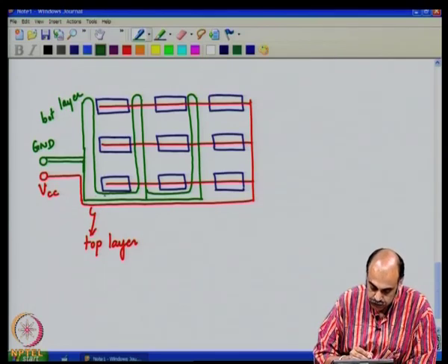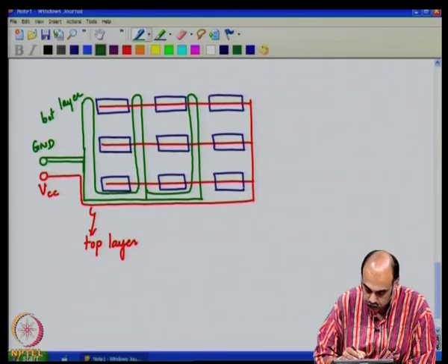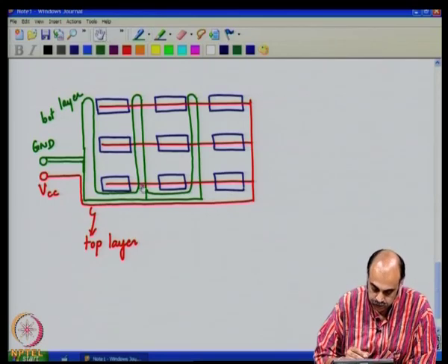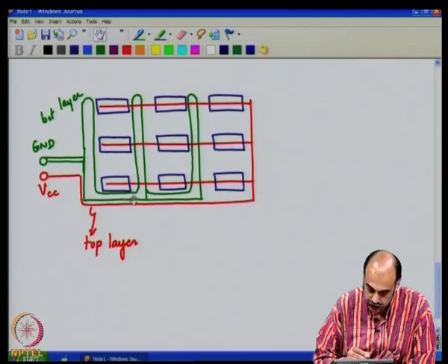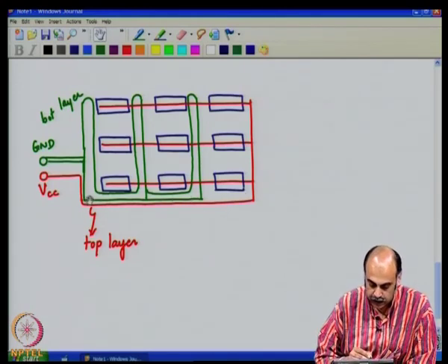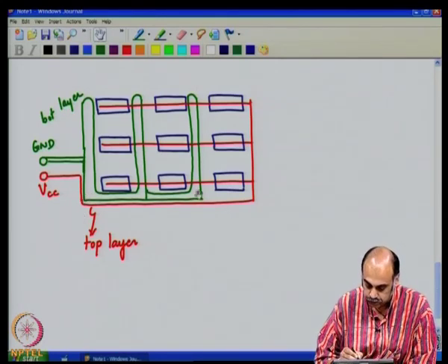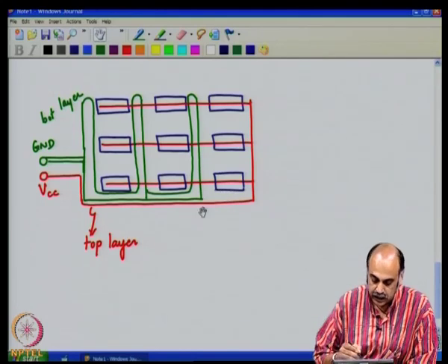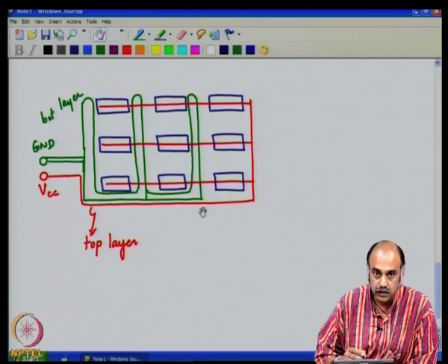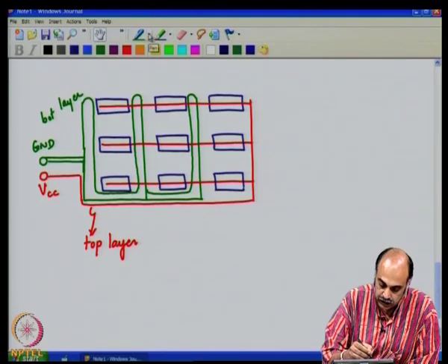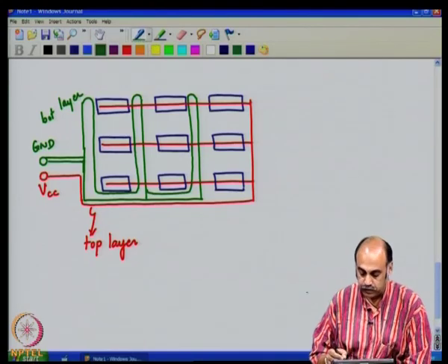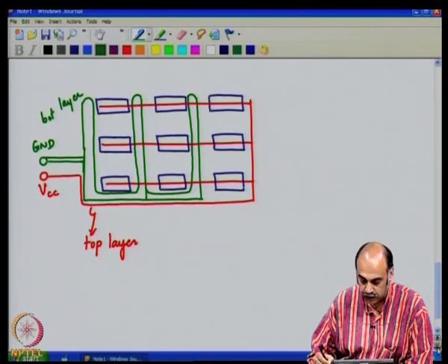Now, by trying to keep majority of the ground and the supply here in this zone, you can make the ground very thick, ground tracks thick here, and then the supply on the top layer to overlap on the thick ground layer, so that you can try to have a good level of distributed capacitance at this portion. So that each of these lengths will have some capacitive impedance here to supply the spiky currents. So, this is one type of ground routing which is very common.